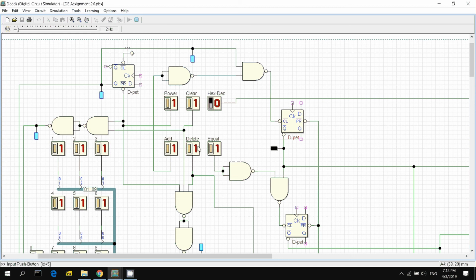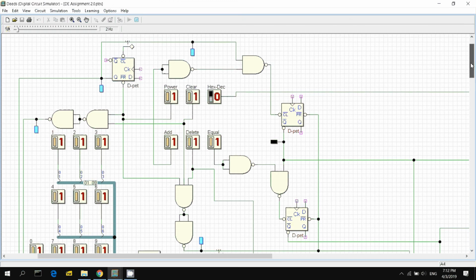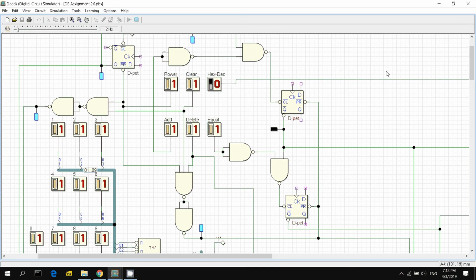What happens is it will kill the add state and go back to the initial state where the user has to choose the first number. So this D latch is just to keep track of the state only. And when you want to reset the state, you just connect to either clear or preset, and the other way around you connect to the opposite. Your choice, it's the same.